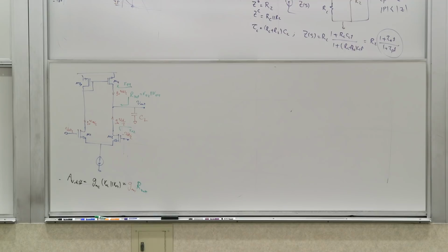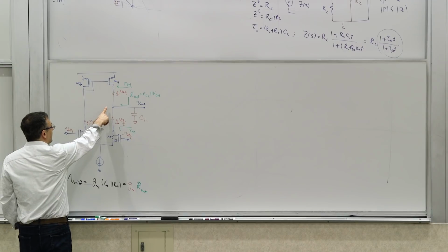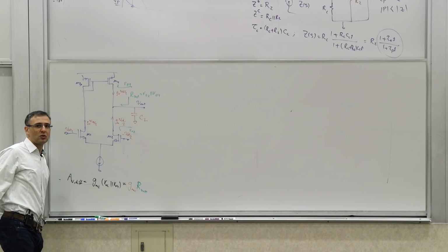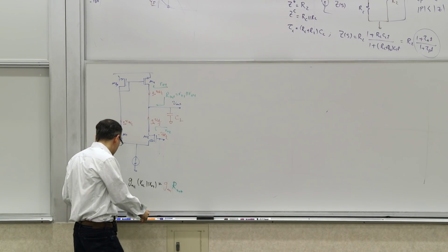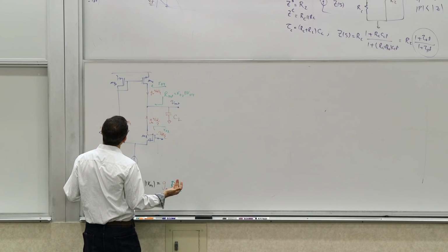Any question? Why did I switch GM1 and GM2? They're the same thing. If they're differential, they're balanced. If the stage is balanced, they're the same. It doesn't matter, you can write GM2. Okay. The high impedance node is here. You have some load capacitance. So that forms potentially a large time constant, right? So let's call it tau 1. Now, what else should I worry about?